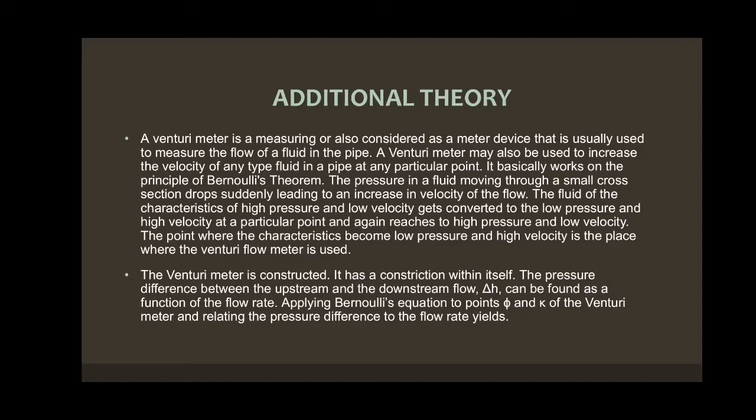For example, if the fluid is at high pressure and low velocity at a particular point, it is converted into low pressure and high velocity. That is the job of the venturi meter, which increases the velocity of a fluid. In a venturi meter, the principle applied is the Bernoulli principle. Next, I will explain the equation of the Bernoulli principle that will be used in the venturi meter.